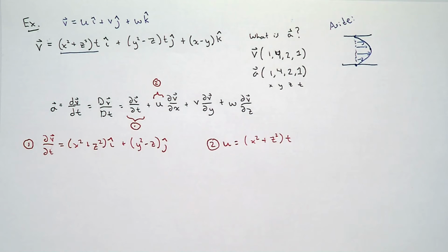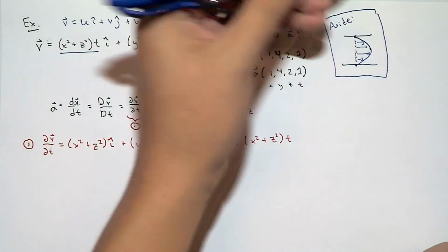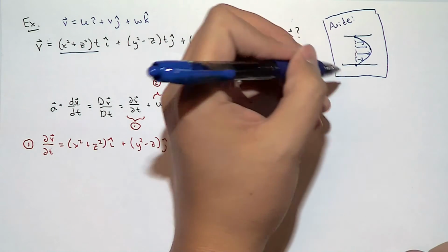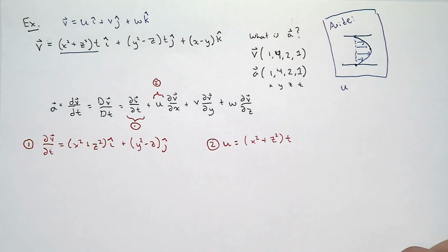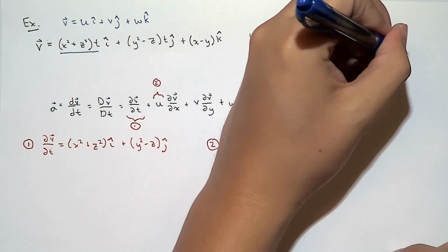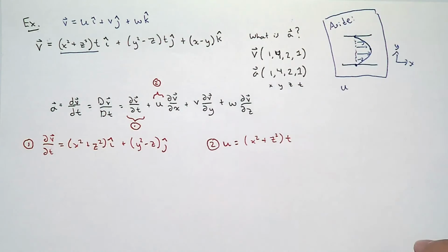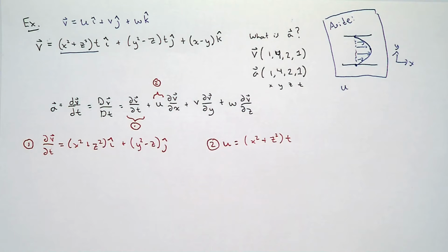Now for flow in a pipe, we're looking at incompressible developed flow. We're going to talk about what all that means later. The x component of the velocity, which is just a component along the center line of the pipe, or along the longitudinal direction of the pipe, varies with what position? I'm just going to give you some coordinates here. We have x, we have y, z would be normal to the board. So my question would be, the x component of your velocity, just for this slice of fluid that we're looking at, this two-dimensional slice, varies with what variable?